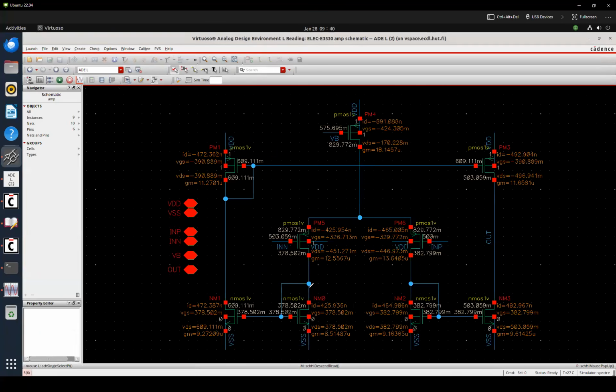This is because you see that here, node and node. All the internal nodes from input to output, from this side and from this side, all the nodes except for output have resistance value 1 over gm, right? This one is also 1 over gm. This one is also 1 over gm. And for output node resistance, what is the value? Do you remember? Output resistance?